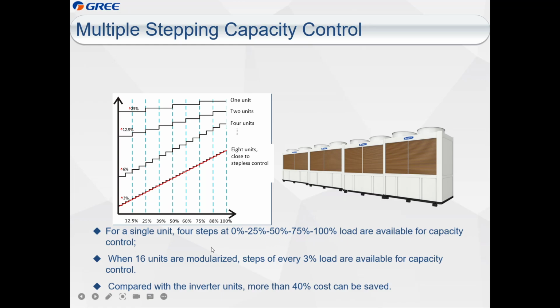And I need the data to show the COP value of our unit at these conditions, the efficiency, to talk with the customer and calculate the IPLV for the customer.